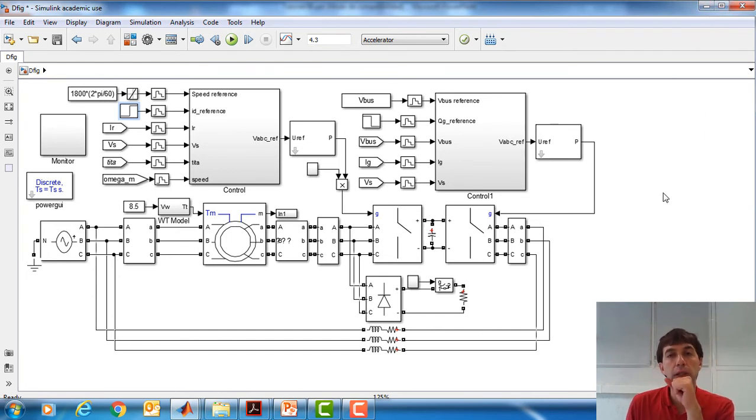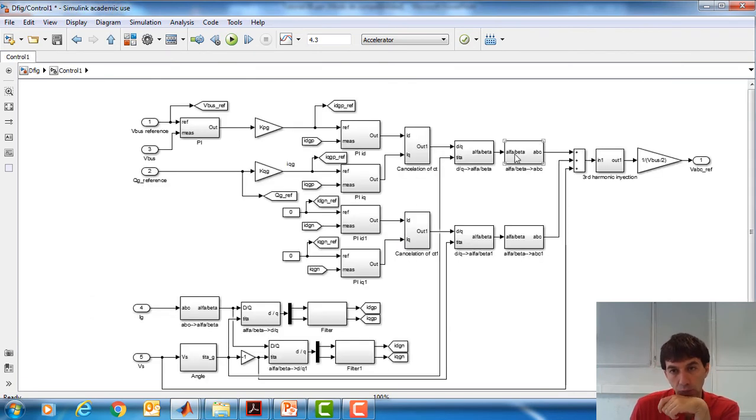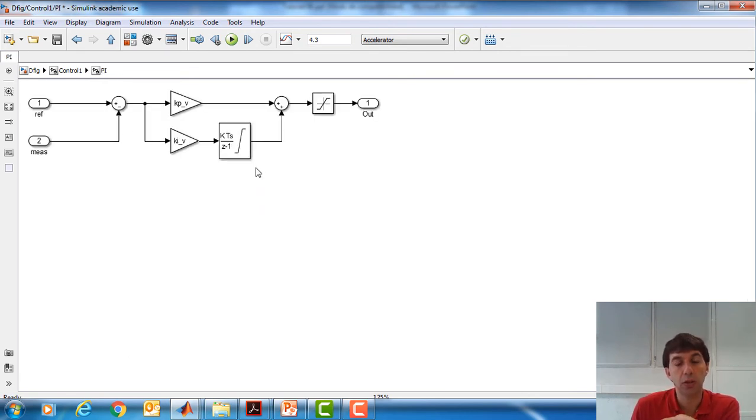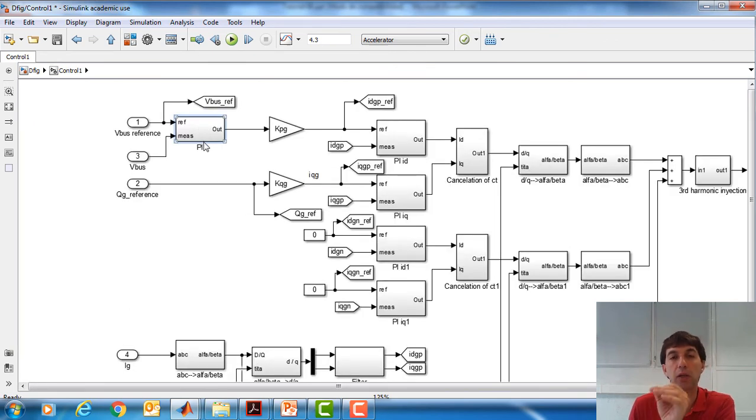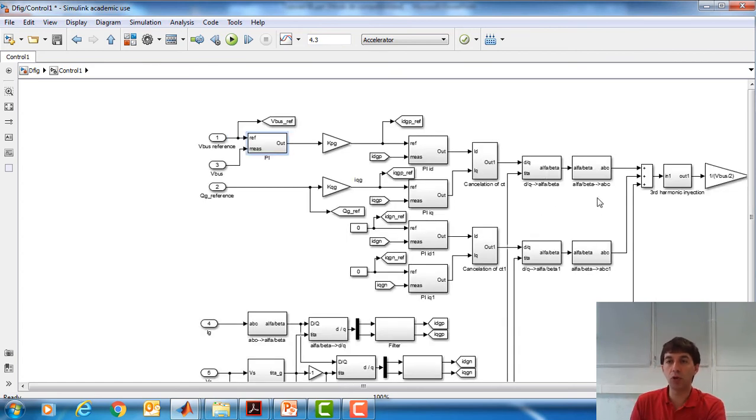However, there is one last thing. As now here we are dealing with two pairs of current loops, 4 current loops, it is very recommendable to make the dynamics of this DC boost voltage regulator a little bit slower, because now there are many sequences, many PI controllers, many loops working all together.